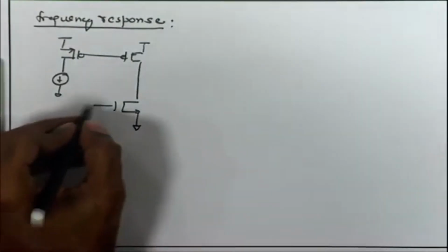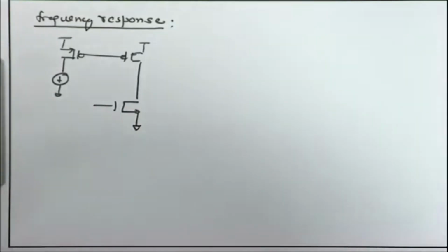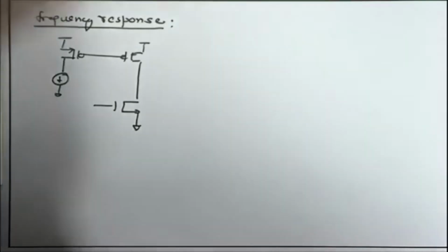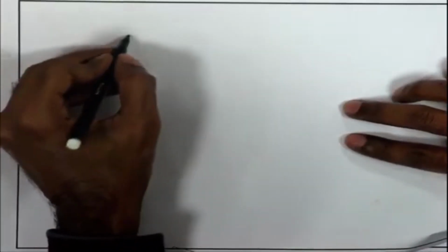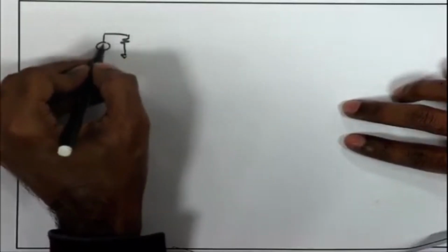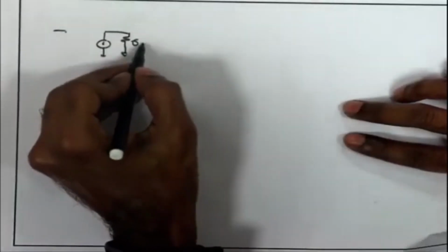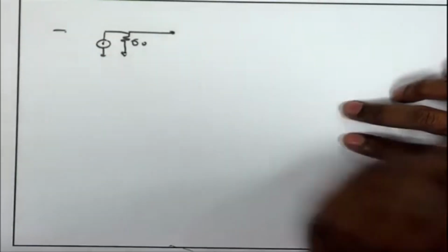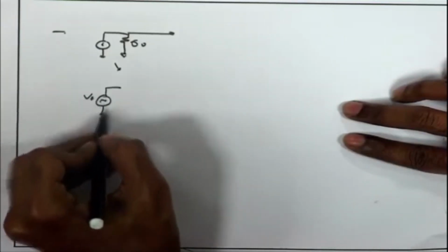Now, let us assume that the source is not an ideal source, you have some source resistance. So, in general it may be driven by some other amplifier stage, right. So, it may be coming from some other common source amplifier or differential amplifier, and we know that the output port of such an amplifier, any other amplifier, you can represent as a current source and the corresponding RO which is going to the next stage. I can also represent it as an equivalent voltage source VO and RS.